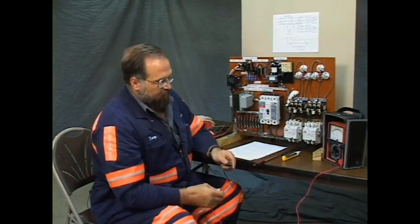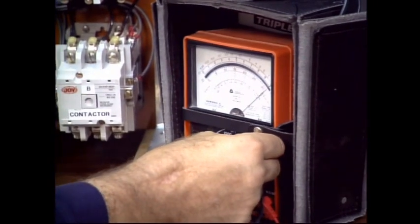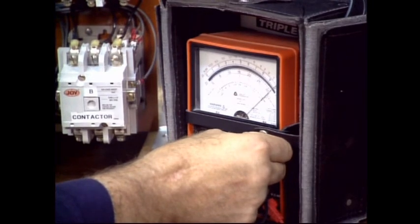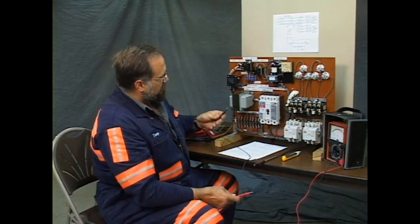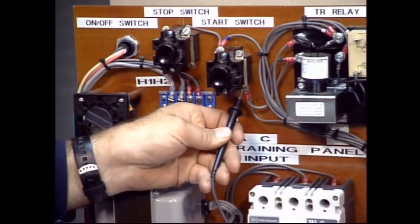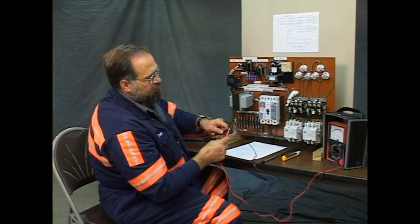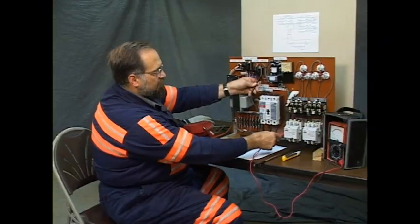Take our test instrument. Let's zero this, make sure we're still calibrated. Let's touch that up just a little bit. Okay. Now, I'm going to read from the load side of the start switch, which is here, to the line side of the A coil, to there. I should have a circuit, but I don't. Let me make sure my meter's working correctly, because that really should read. Meter's working fine. Shows no circuit though.